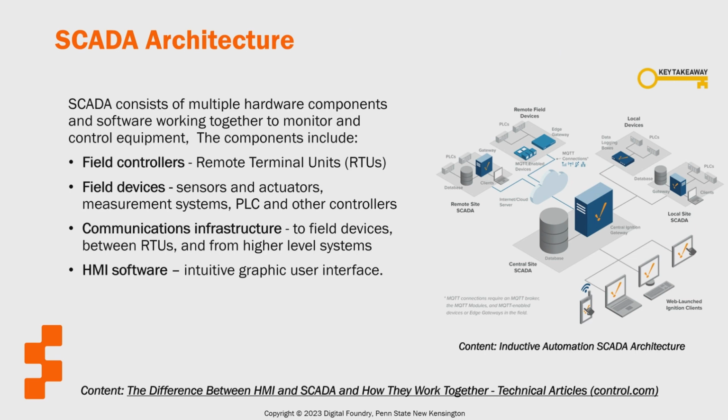Field controllers, or remote terminal units, RTUs, are compact microprocessor-based control units installed at several different physical locations of the system. These devices share many similarities with PLCs, but have some distinct characteristics. RTUs serve to monitor and control one or more field devices at a time. These field devices can be sensors, valve actuators, and many others, both analog and digital.